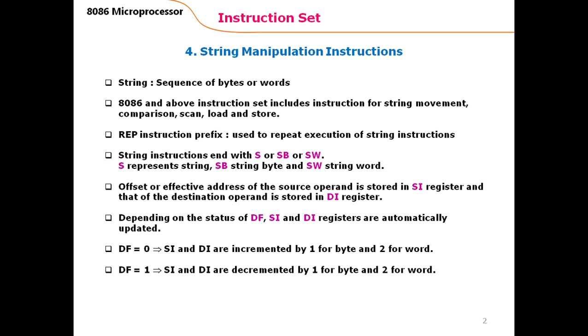In 8086 and above microprocessors, the instruction set includes different instructions to move strings from one place in the memory to the other, to compare string data, to search or scan string data, to load the accumulator from the memory, and to store the accumulator into the memory.